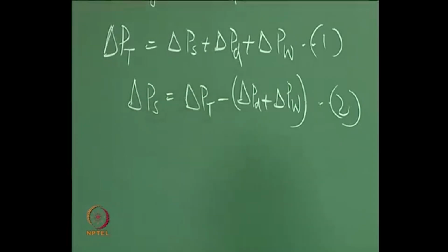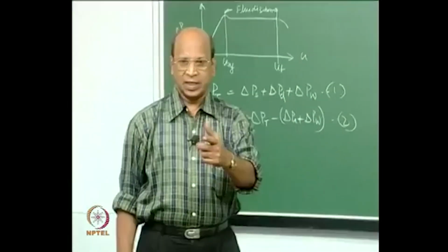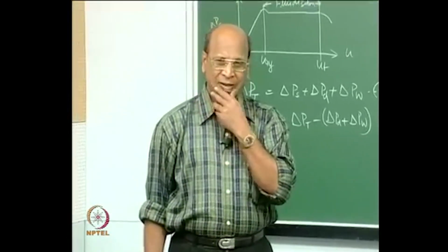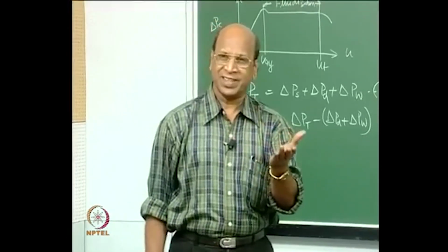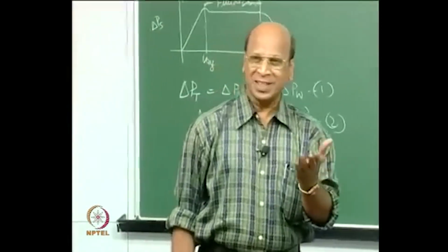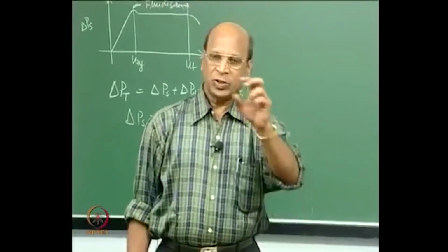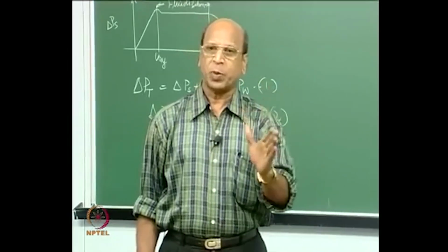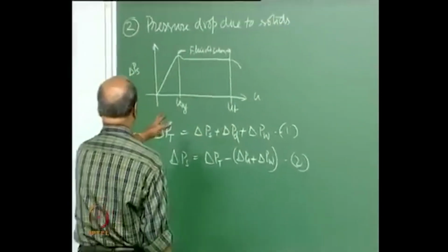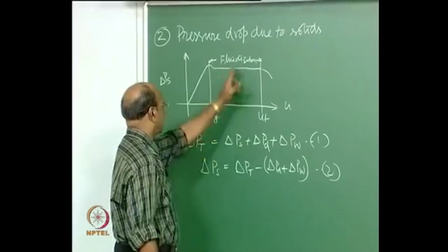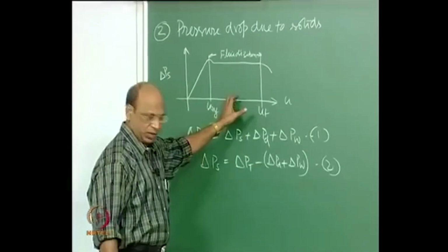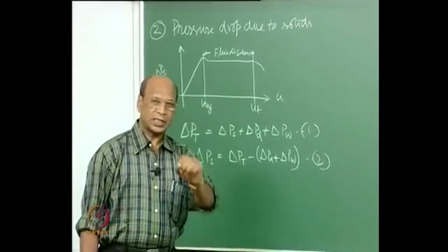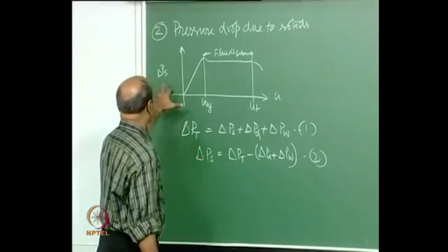In the picture, before putting the solids, we have only walls and the distributor plate. You just measure at various velocities what the delta P will be, and then for every flow rate you subtract these values, and then you will get this.